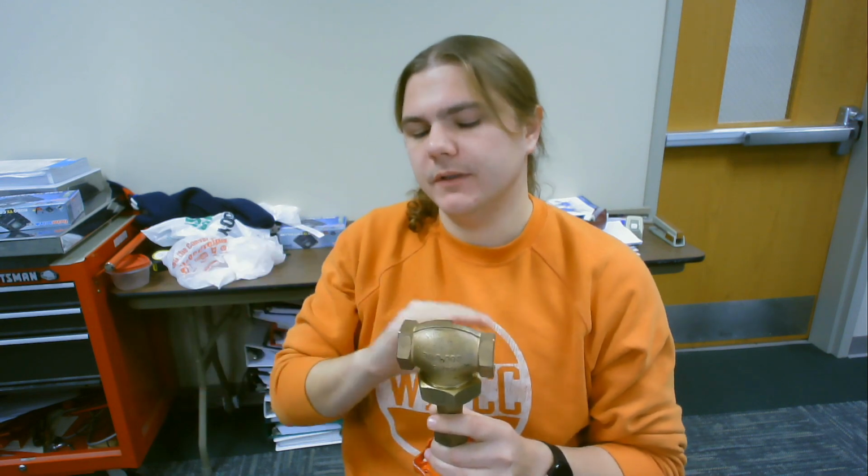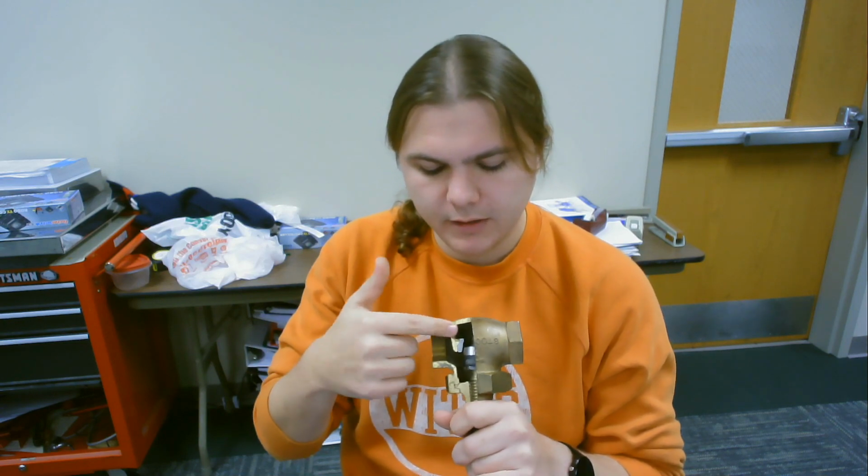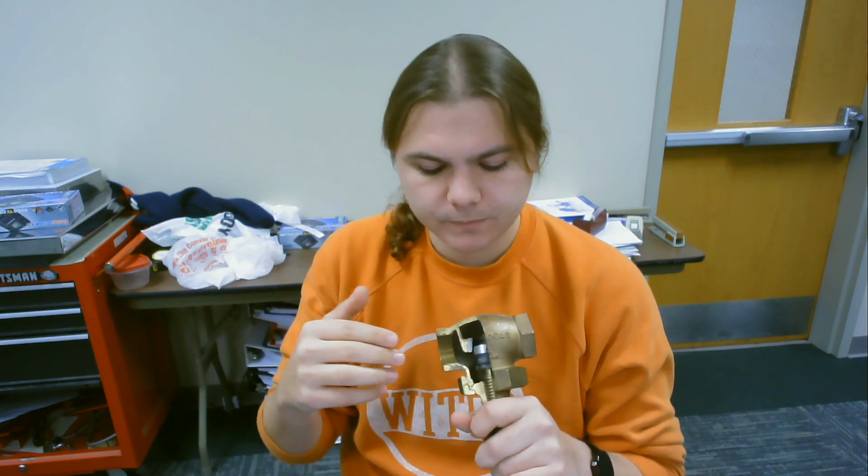What a section view does is takes a part like this valve here, and on, say, in this situation, the top view, I'm going to put a cutting line on it. And when I have that cutting line on my front view, in this situation, I'll have my section view. So it cuts away, in this situation, half of the part, and now I can see all the internal features of this valve or whatever part you're working on.